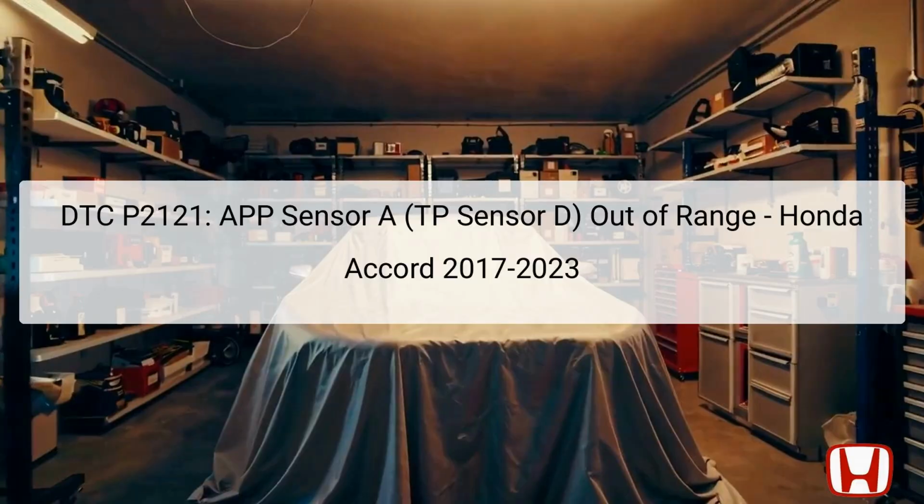The Diagnostic Trouble Code, DTC P2121, is associated with the Accelerator Pedal Position, APP, sensor A, specifically the Throttle Position, TP, sensor D. This code indicates that the signal received from this sensor is out of the expected range. The APP sensor is a critical component in determining how much power the engine should produce based on the driver's input via the accelerator pedal.